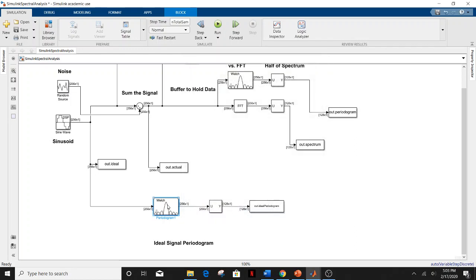And so that's going to output a spectrum with the number of FFT points coefficients, but that spectrum is going to be symmetrical since we're looking at power. Especially, there's no difference between the left side and the right side of the data because we have no difference in phase. And so all we really need to look at is 1/2 of the spectrum.